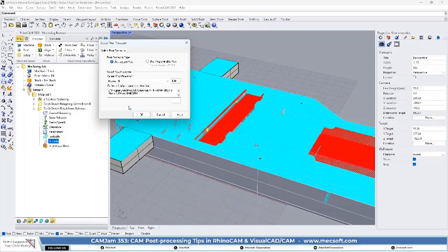That's an important thing to keep in mind, because we run into that all the time. We do make some edits for people for post-processing and they stick it into the same folder, and then when they get a newer version, it overwrites it if the name of the post-processor is the same. So what we would suggest is to create a separate folder for any of your custom posts, or even if you don't want to change it and you don't want to look at all these posts in the folder. That's what we would recommend.